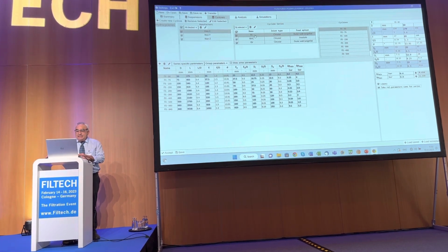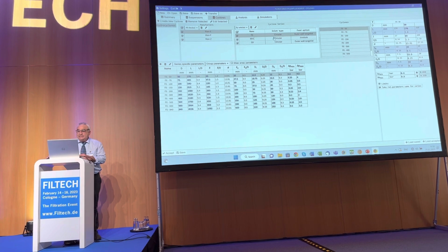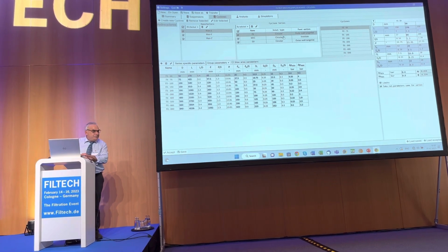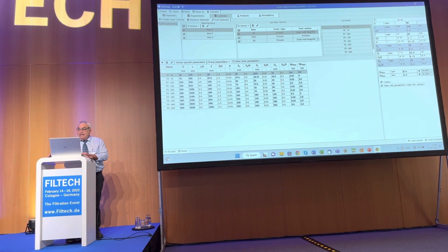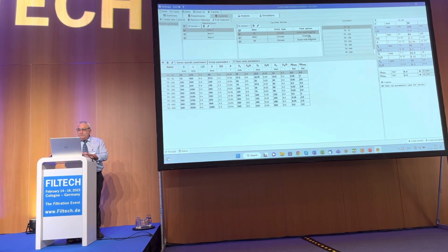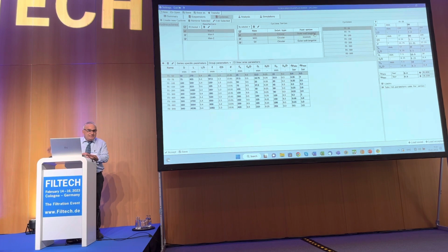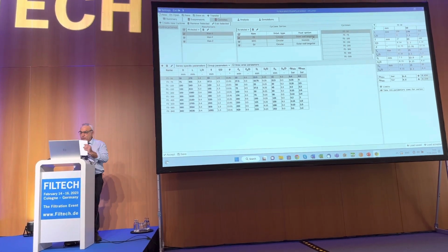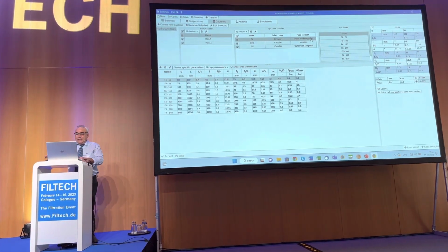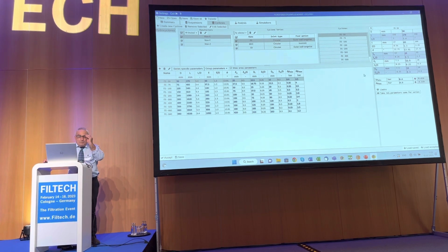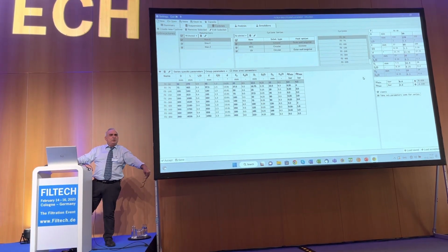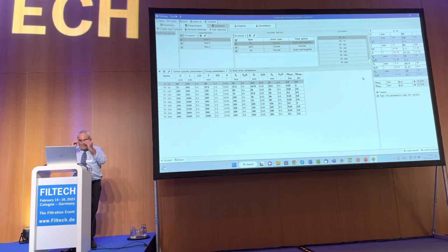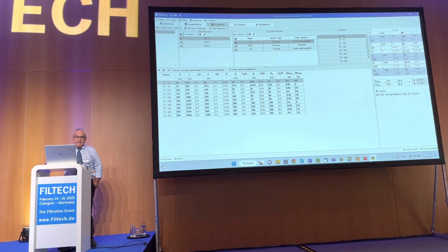And here, that is the name of the cyclone series. That is the inlet type. It can be circular or rectangular. And here, that is the feed option. It can be involute, outer wall, tangential, that is the default case, and so on. So we have here, as last, the minimal and maximal pressure depending on the diameter of the cyclone. So again, here, that is the cyclone database.